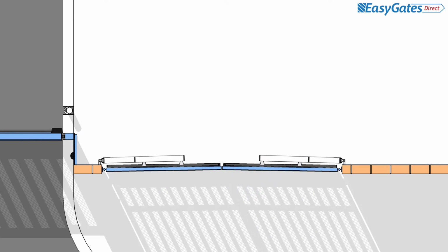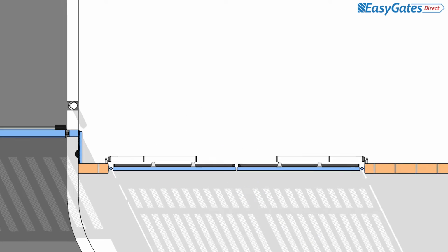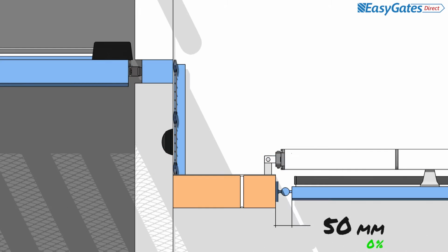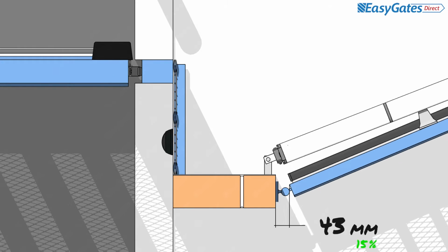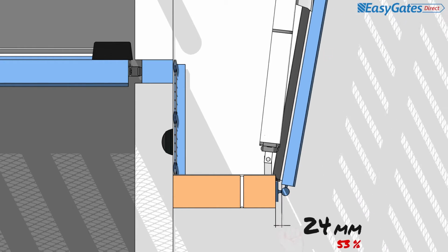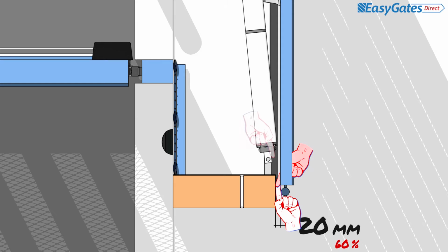Here we can see an example of a reducing hinge gap, and how easily a body part could become crushed in this area. Careful consideration should be taken when assessing this hazard, as multiple crushing points and shearing hazards can be present depending on the design of the gate.